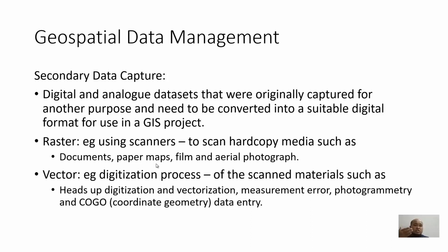Photogrammetry is by taking photos, right? And COGO means coordinate geometry data entry. So coordinate geometry is simply like the pinpoint that I mentioned. You just register a single point, so the system will understand that particular single point with coordinates and elevation and so on. It does not understand it as an entire surface. So that is COGO.